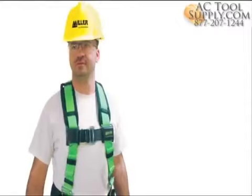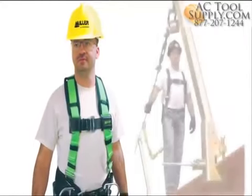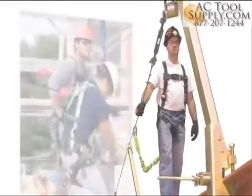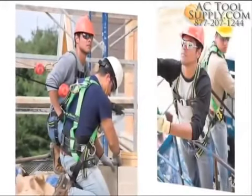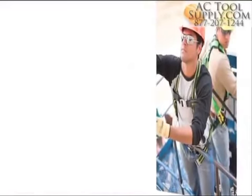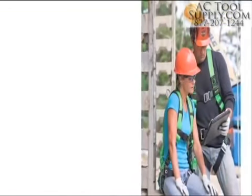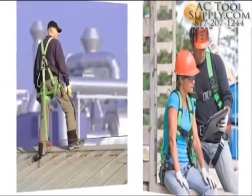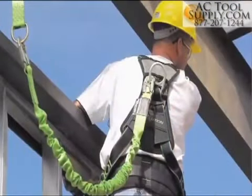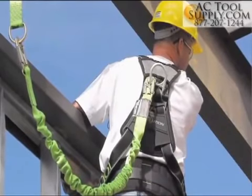The harness style should be selected based on the type of work being performed and the overall work environment. The full body harness offers an inherently high safety factor, since fall forces are distributed throughout the body over many webbing components, including chest, shoulder, waist, and legs. In addition to distributing forces throughout the body, a properly fitted full body harness keeps the worker suspended upright while